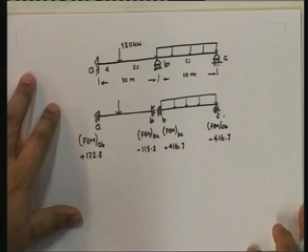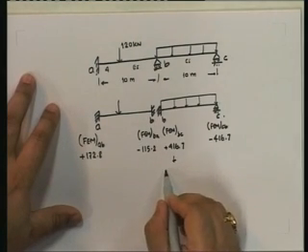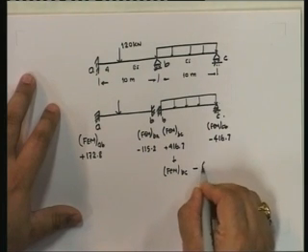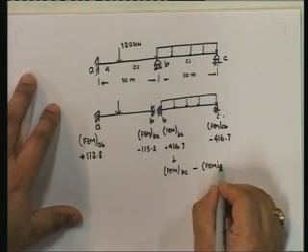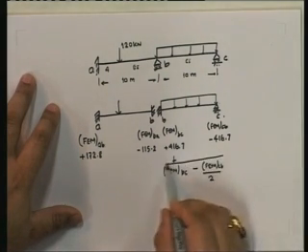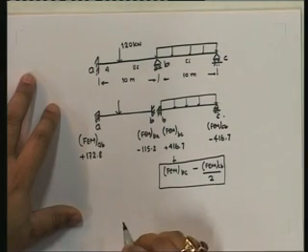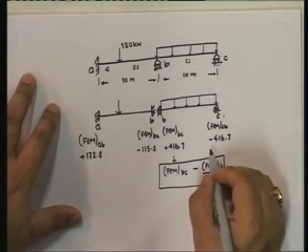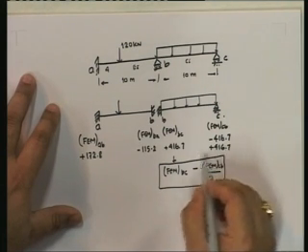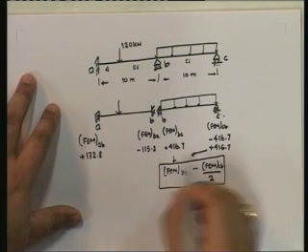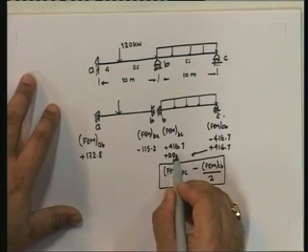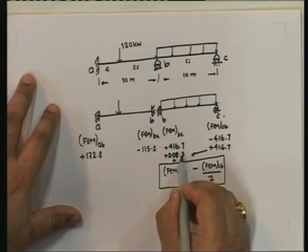Okay. Now remember, what was the modified fixed end moment here? The modified fixed end moment, remember that? We had computed this. Now my point over here is this: isn't this the same as balancing the moment here and then carrying over half, which is basically plus 208.3?